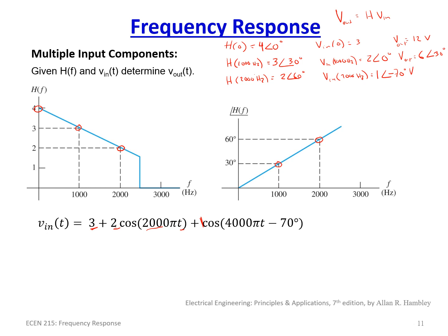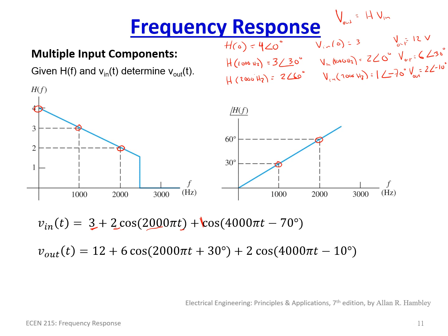And then we have V out here equal to 2 times 1 with a phase of minus 70. So that'll be 60 minus 70. So that is added together. So we end up with 2, minus 10 degrees. And you can see here, that's what we got here on the answer below.